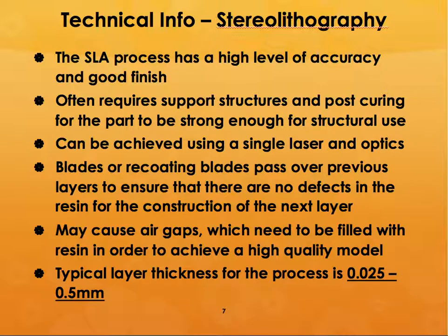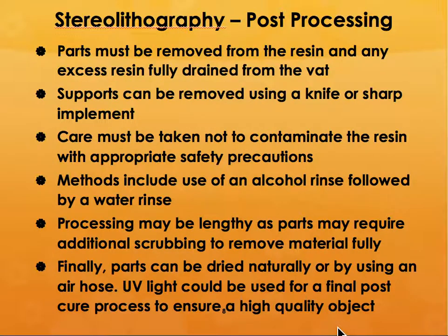Typical layer thicknesses are of the order of 25 microns to 500 microns. So if you know that the wall thicknesses are pretty uniform, then you don't need such a small layer thickness. You can use much larger layer thicknesses.